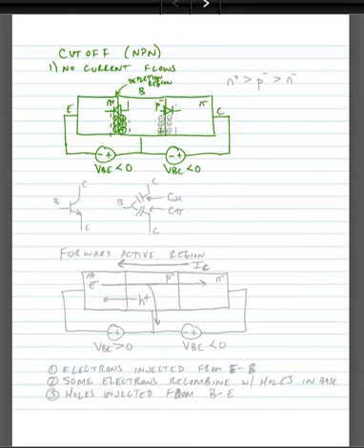The same thing occurs at the PN junction between the base and the collector. The electron hole pairs are bound to one another and don't want to move, and so we get a depletion region there as well. Now one would note that the concentration of the carriers has to do with how thick the depletion region is. So the N plus region, which has more carriers, would be thinner than the P minus region, which has fewer carriers, and hence would need a wider region to have the same amount of charge to bind to every particle in the N plus region.